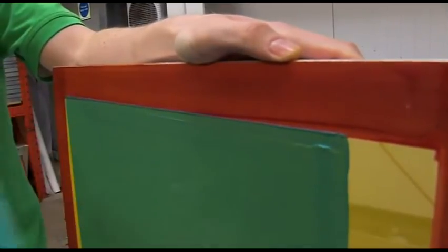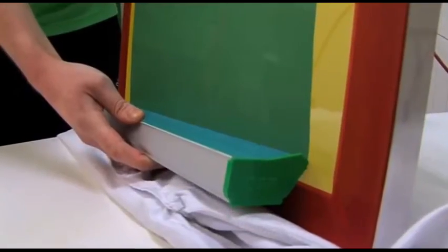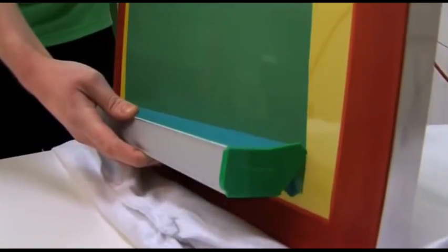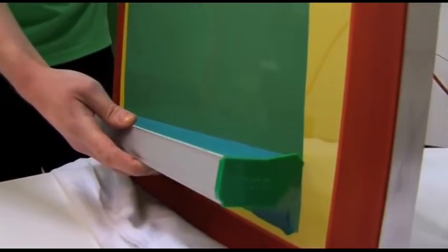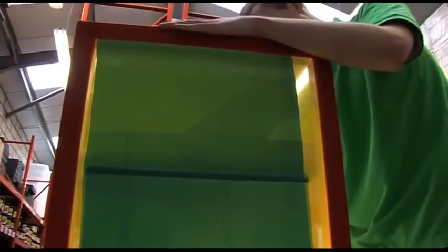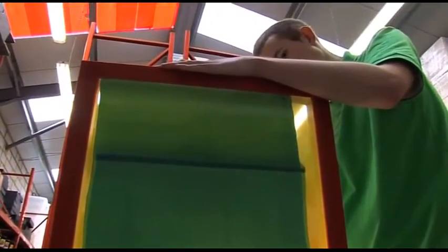If you are a beginner and feel you may not have an even coat, tilt your trough towards you and perform an even scoop quickly and gently back across your screen. Now repeat on the print side. There are many coating methods, and it is down to personal printing preference. The type of printing jobs a screen printer has will determine his preference.